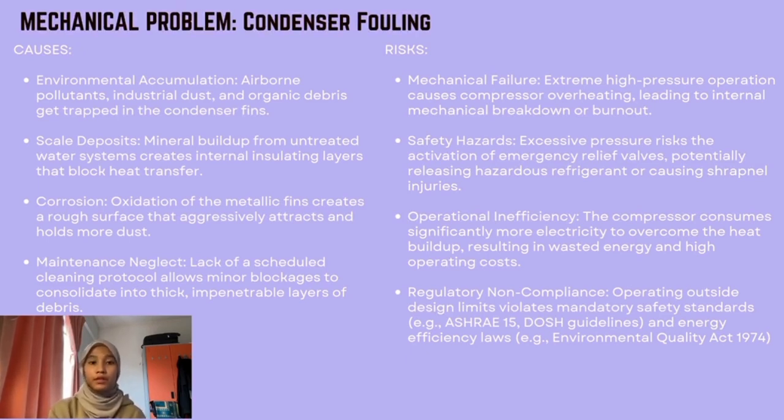And we have risks. Risks are significant. Firstly, we have mechanical failure. High pressure causes compressor overheating and breakdown. Second, we have safety hazards. Excessive pressure can trigger emergency relief valves, releasing refrigerant or causing shrapnel injuries. And then we have operational inefficiency. The compressor uses more electricity, wasting energy and raising costs. Regulatory non-compliance. Operating outside design limits violates safety standards like ASHRAE 15 and energy laws such as the Environmental Quality Act